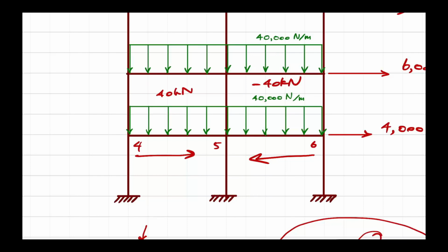So that depends on the program, but it does matter when you apply the load on your member, which is in or refers to the local coordinate. The direction does matter. How you start and how you end the node does matter. The program will not understand you automatically, right? This is the protocol that we use to write the program. So be careful.